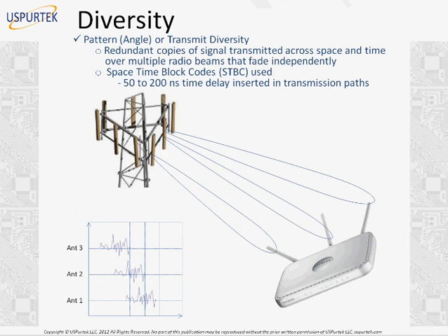Okay, so Veda Prabhu has a question. What about polarization diversity in circular polarization? Well, when you do circular polarization, you are actually transmitting the same signal over the vertical and the horizontal, right? So in that case, the same principle applies actually. In circular polarization, it's automatically achieved. If you lose the vertical component, you still have the horizontal component on the same signal, right? So it's a very good question you have asked.